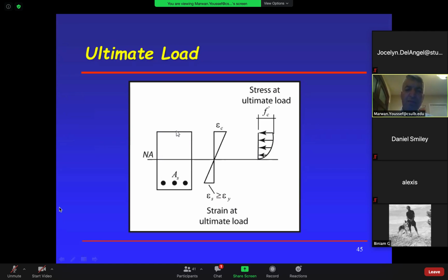If there is a compression at the top, that means there is a compression force, and the force yields a stress. Why? Because the stress equals force divided by area. And the area usually is constant, or we know the area that the force is applied on. So we know there is a compressive stress and it gives us compressive strain. How do we get from stress to strain?